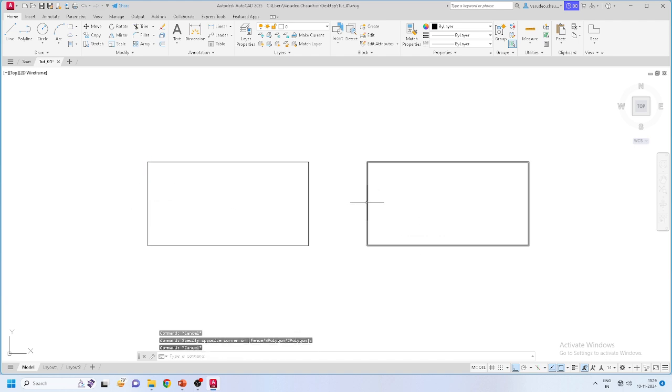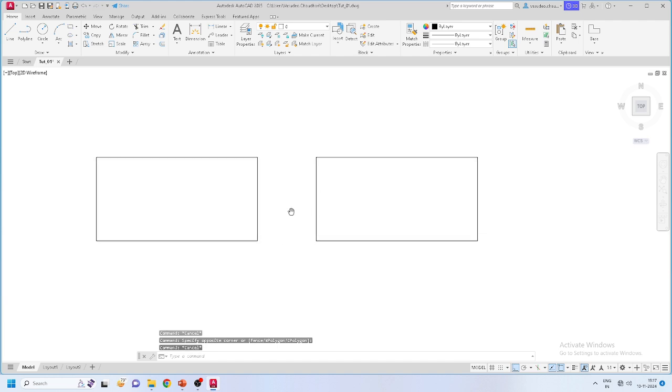But on the other hand, if you click on the polyline, all lines will be selected. Here all lines are connected. There are a number of benefits of polyline, and sometimes we misuse line only. In fact, you can convert a polyline into simple lines, or from single line segments to a polyline. So that is also possible.